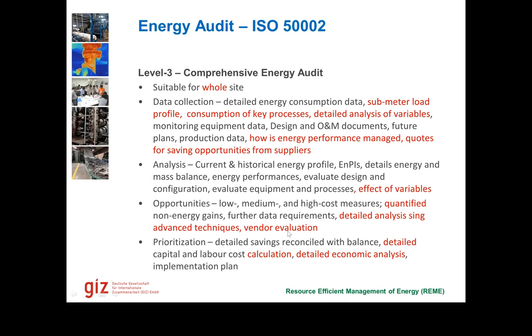When we come to level 3 comprehensive energy audit, it is suitable for a whole site or a set of sites or a group of companies. The red points that I have highlighted are the points which are different from level 2. So here we need to have sub-meter level data, sub-meter level load profile, not only at the main meters, but also at the sub-meters. Then we also need to have consumption of the processes themselves.